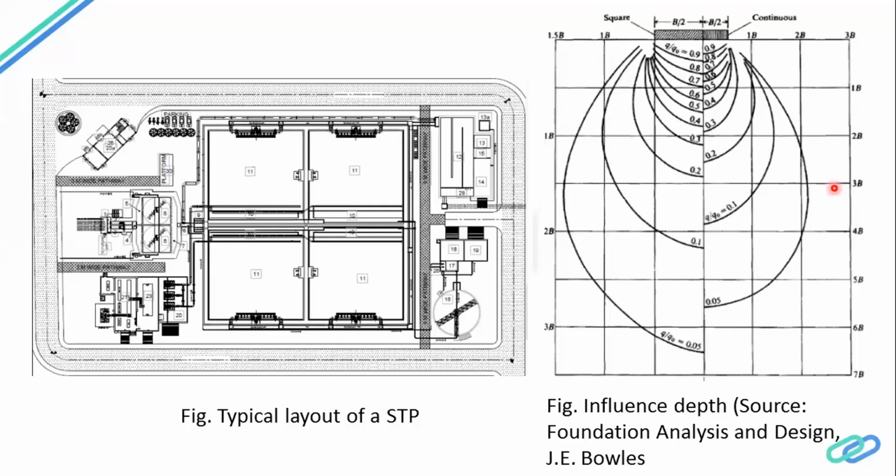Another important thing to be noted here is, depending upon the location, it will vary. Suppose we have a project in Kolkata. Usually Kolkata soil is very weak. We'll have very soft clay in the top portion, it may be up to 15 meters, with very low SPT values. So in such a case, we may have to go for pile foundations, and we have to go for a deeper borehole. I have that idea only because I have prior knowledge of Kolkata soil.